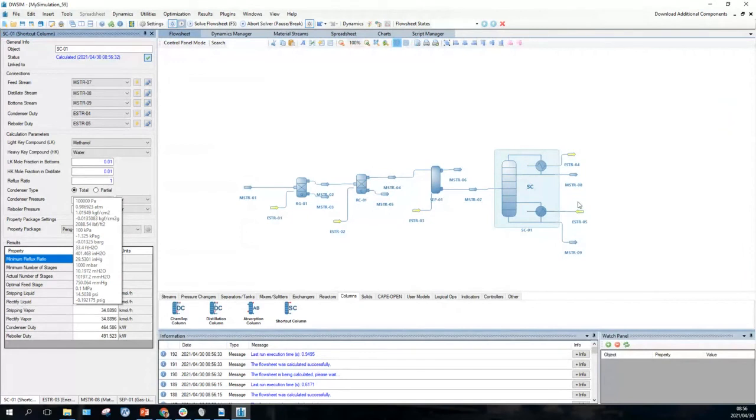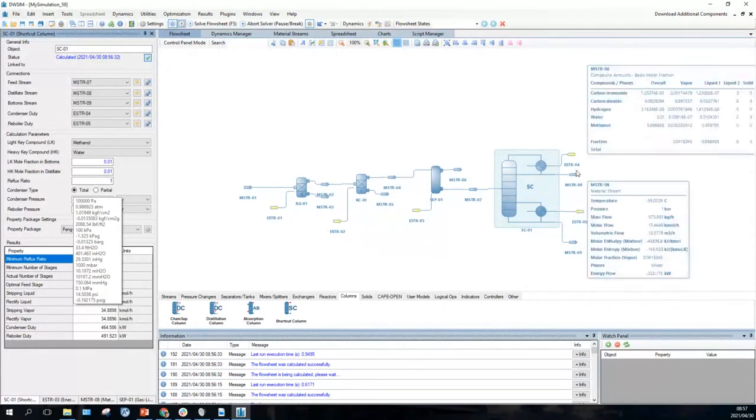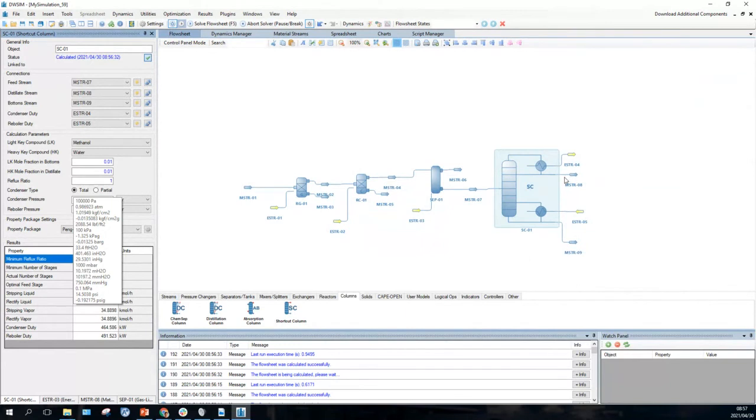All right, so let's see. We've done condenser temperature, change it. It should be now 62. Now use a controller block. Okay, so this is cool, but it's not the one I want. I'm looking for something where we can change the temperature from 600 up to 1,000 on the Gibbs reactor, and see how the yield changes. So this logical operator is not doing that, but it is doing something fairly cool. So I just wanted to show you how to use these blocks.